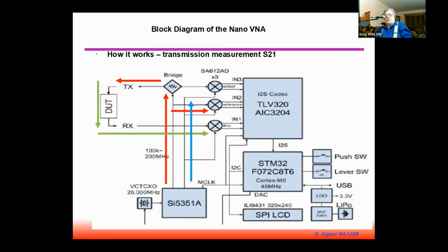You can calculate phase relationships. So one thing that's happening here is these signals, as they're digitized in the A to D and sent over to the microprocessor, they do that in a complex math or vector math format. And so not only is the amplitude of the signal conveyed to the microprocessor, but also the phase of the signal, so they can do complex mathematical operations of vector quantity. So not only can they measure the amplitude and strength of the signal, but they can measure the phase relationship between the various signals.